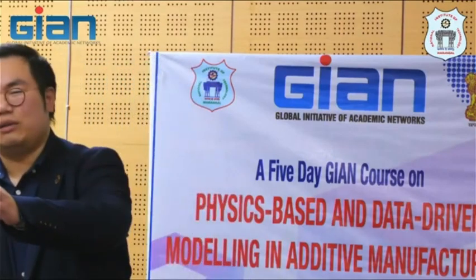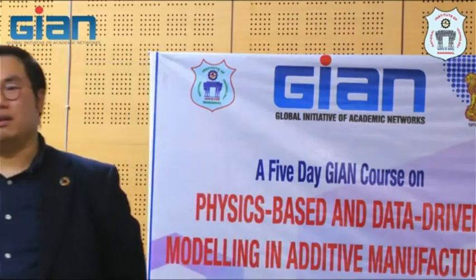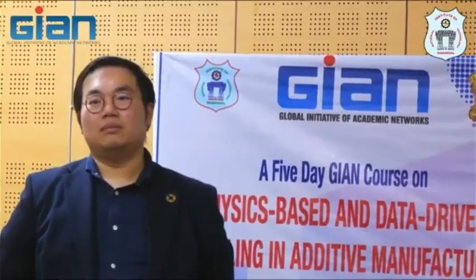Say again, I'm not getting it. So suppose you were referring to the non-equilibrium temperature-dependent properties of the material, like Ti64, AlSi. It's not non-equilibrium. We said temperature-dependent property. Okay, so due to the non-equilibrium nature of the components, meaning precipitation and all those things, there could be some effect on the temperature-dependent property as well. Those effects will be more prominent below the solidus temperature. You asked a very good question, but